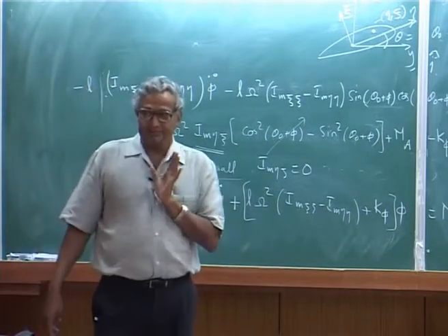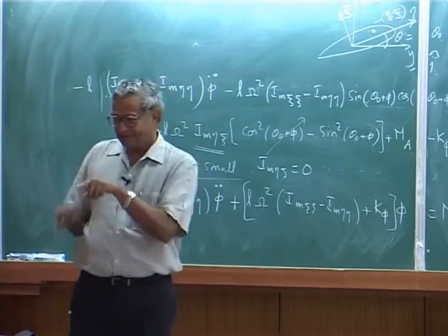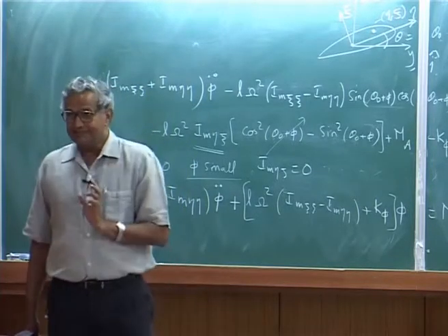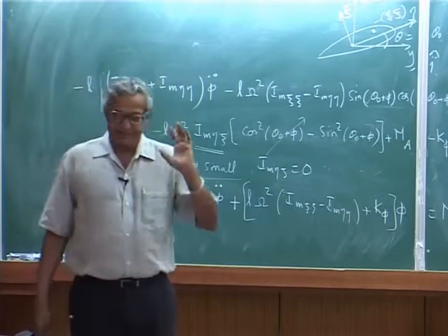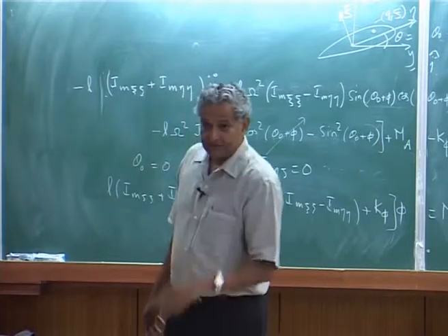So, you do not want to do that, and if aerodynamics is ahead of the feathering axis, lift will twist the pitch angle, you can have some kind of a divergence type of problem which you have in the fixed wing.